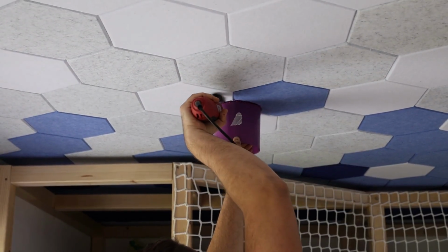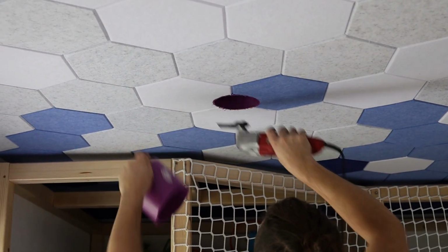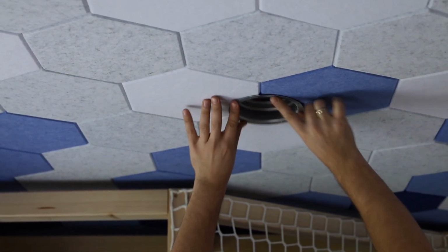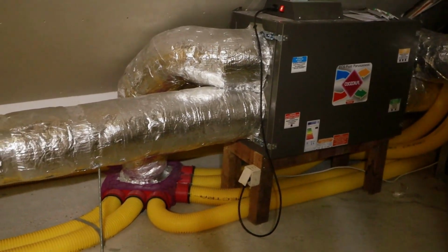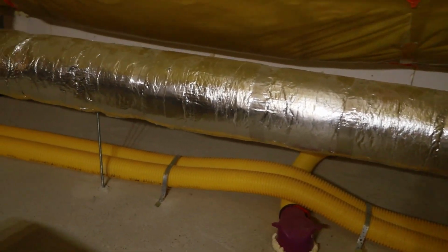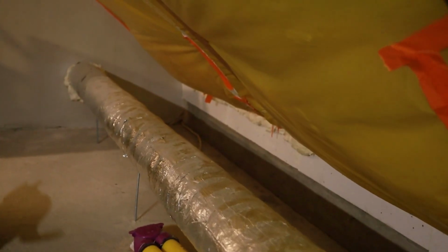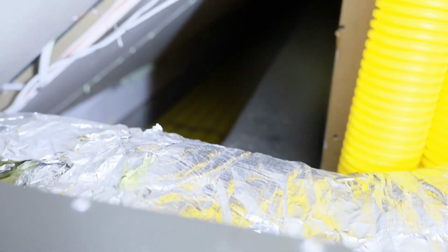So, to summarize the advantages of the MAXVENT system, it's ease of installation and a very competitive price. A larger diameter of ventilation pipes, meaning 90 mm, rather than the standard. Consequently, we need fewer ducts and have fewer connections to make, where a connection is, as always, the most critical point for the potential occurrence of leaks. Additionally, the geometry of the distribution and expansion boxes is designed with smooth, rounded contours, avoiding any sharp angles. This significantly reduces the aerodynamic drag of the airflow within such an installation.